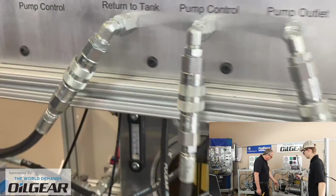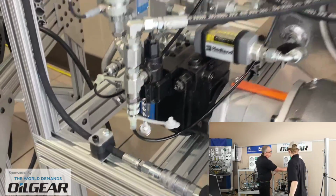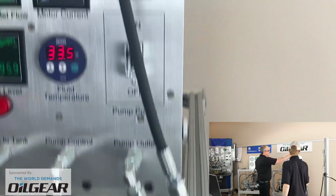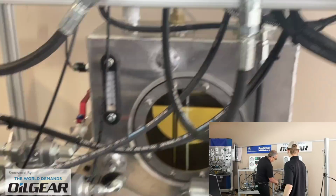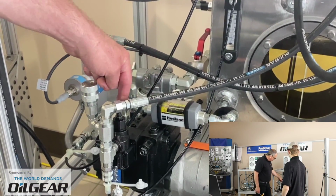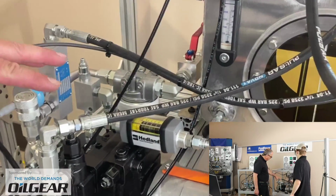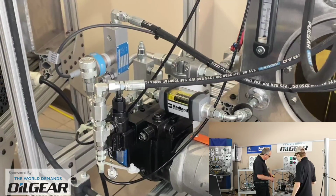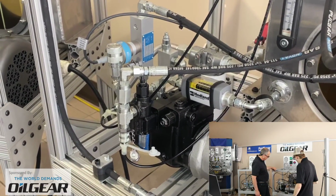Because we do also have the load sense control on there, I have a hose on the pump outlet connected right back into the pump control, and it arrives here, and basically uses the system pressure to knock out the reaction of load sensing. Come back in August and we'll run this pump with load sensing functions and a variety of different loads on a hydraulic system at that time.